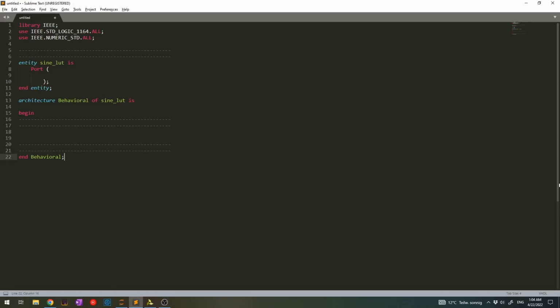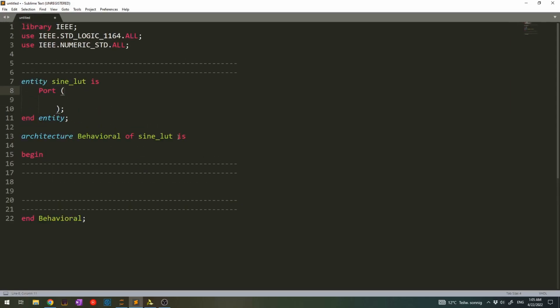Here's Anatolii again. In this video we'll create a simple sine wave based on a lookup table in VHDL. It is not the best way to create a sine wave in FPGA, but it works, and at the beginning it will be useful enough, especially for functions like PWM and so on. So let's get started. As you can see, I already have opened and created a template for the VHDL file.